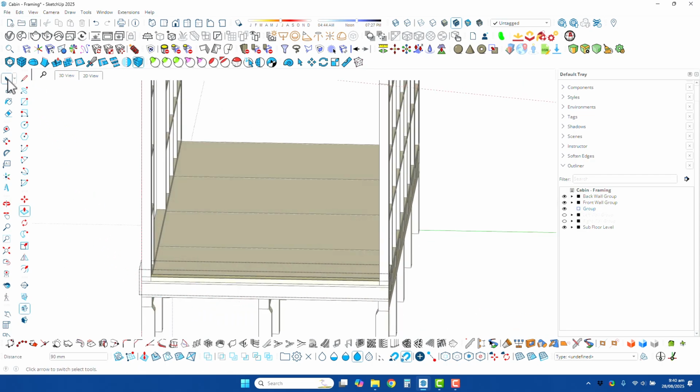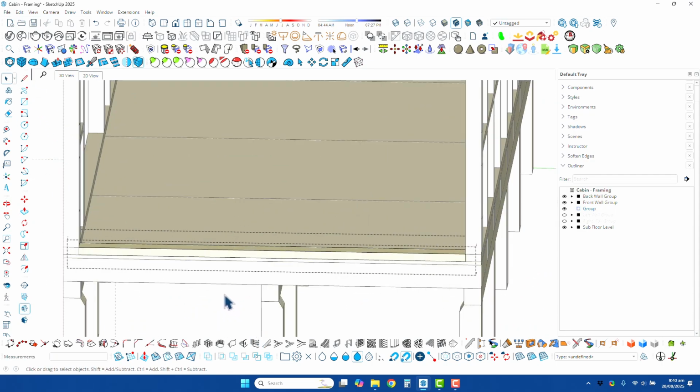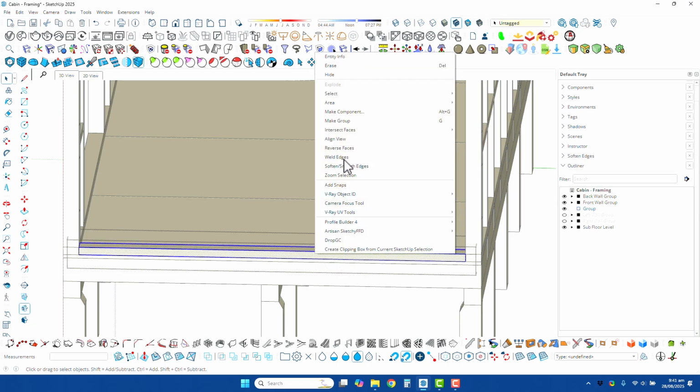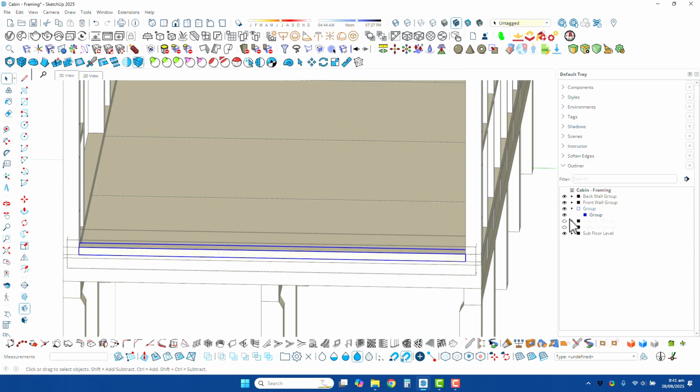Now we want to make that bottom plate a group inside of a group, so you can see the hash line around there, that's our group, and there's some stuff in here which is all editable geometry, lines and surfaces. So we'll get our cursor tool, triple left click, right click, and make a group. And now this group of stuff is inside the group.